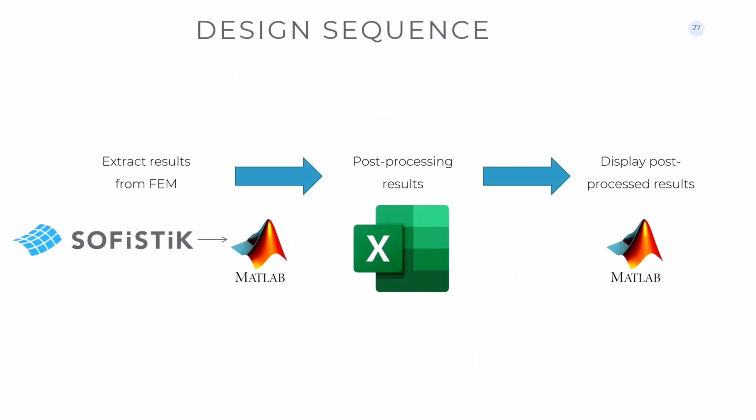By the way, CLT is one of the few materials that is not covered by the Eurocodes. So actually, at the moment, every one of us that works with CLT is working with no umbrella. I mean, the University of Graz in Austria has produced a lot of very interesting documentation. Most of the calculations we do are based on that, but there is no information about this material in the Eurocode, so you're on your own.